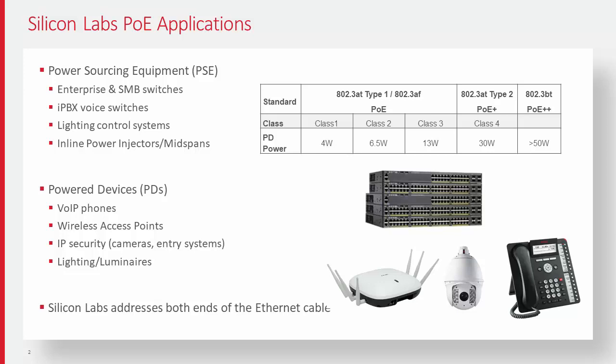So a new standard is coming out now, about to be ratified through the IEEE, and that's called the BT standard. And alongside this BT standard is this huge push for the idea of PoE lighting and the connected ceiling, the idea that Ethernet cables can drive your lighting in a building. And on top of that Ethernet backbone, maybe you have occupancy sensors or something else that can communicate over that Ethernet cable, whose new purpose now is to deliver power to your light instead of AC voltages. That has a lot of advantages in a context of wiring of a building becomes much simpler and less hazardous in a big way. So there's a huge amount of advantages for PoE lighting, but that's just one target market.